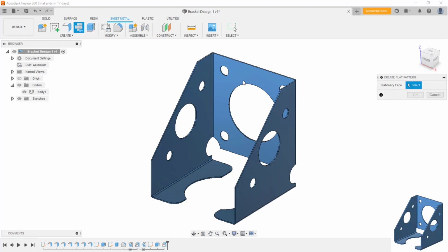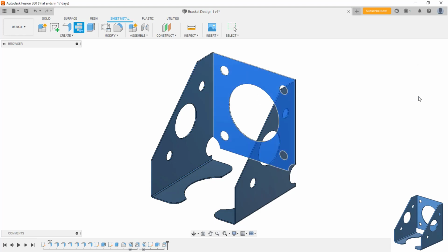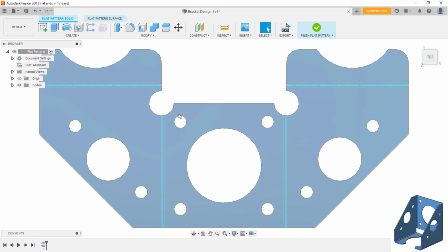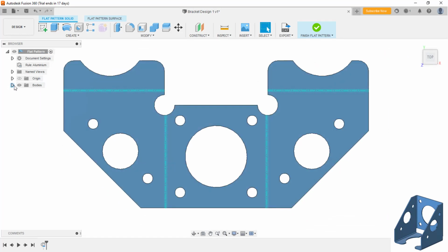So this particular tool, that is create flat pattern, will help you to just have this particular flattened format to export it to DXF format for the further processing like laser cutting and all. Okay, you can even use this bend line, hidden and center lines to just showcase what exactly you're looking for. Okay, so if you want to export it to the DXF format, you can use this option, that is export to DXF. If you want to use the tolerance for the polylines, you can specify it, or else we recommend to keep it as default.